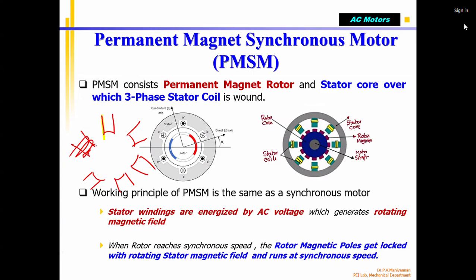This is one coil, that is three-phase. I say this is phase A. We said RGB; sometimes some books call it ABC also. I say this is the R phase, and the coil comes, and exactly these are the pair. This coil comes under this one, and the second coil I say B. This is the B, and the third one is C, that is green, G. Together they are called a pole pair.